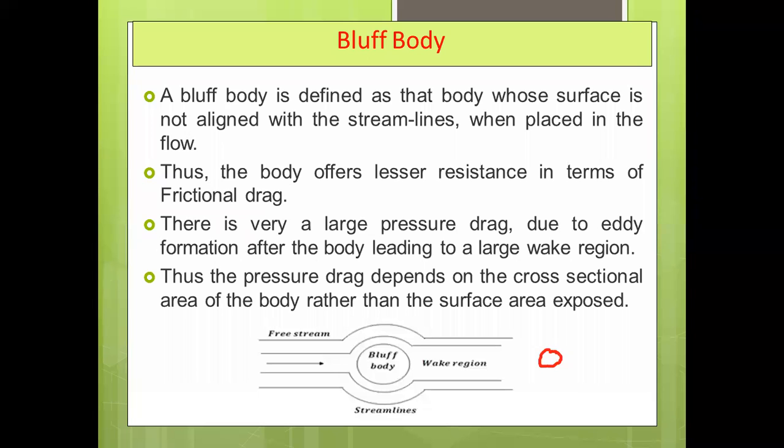There is very large pressure drag due to eddy formation after the body, leading to the large wake region. Okay, so here you can write down streamline body and bluff body. Did everyone notice the difference? The streamline body, its shape is streamlined.